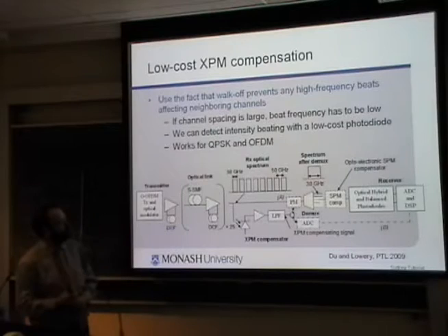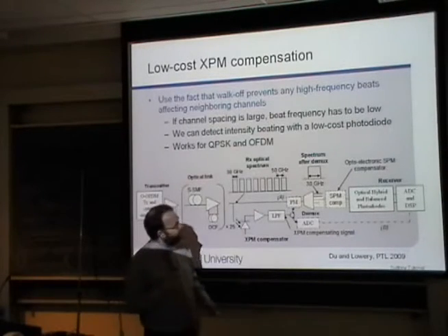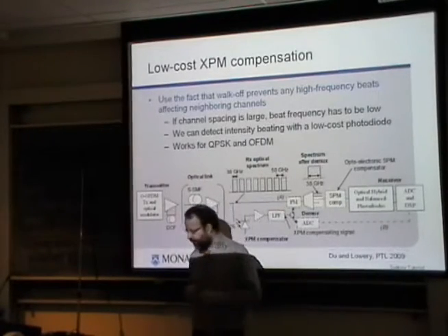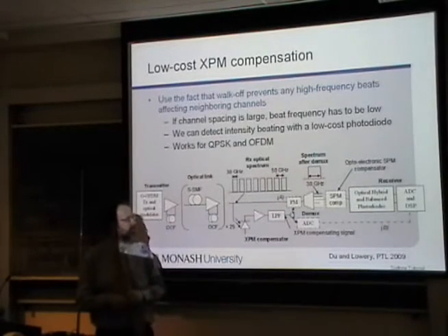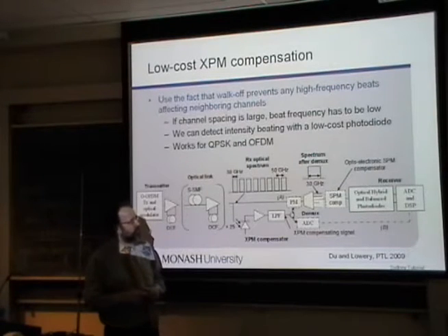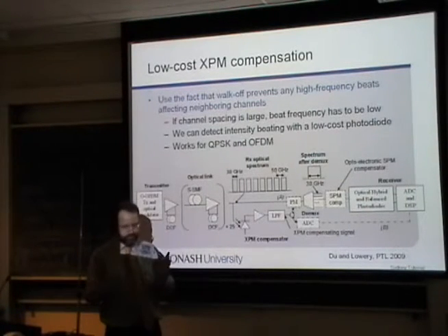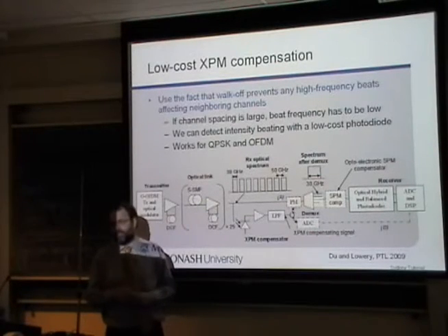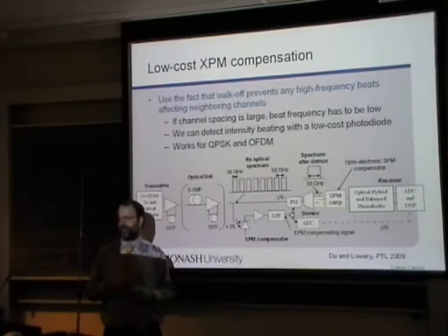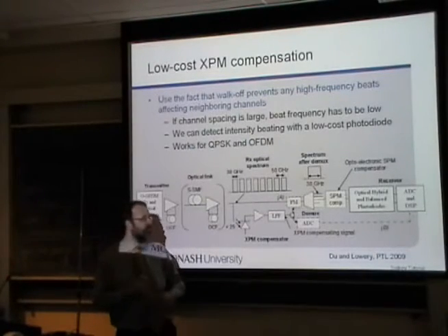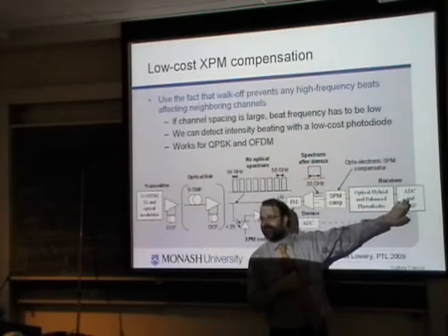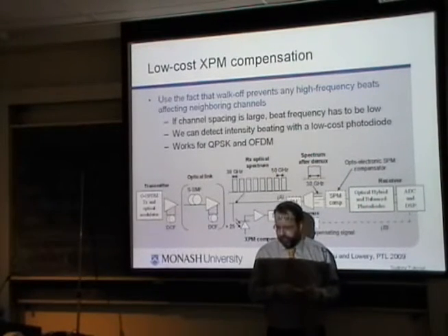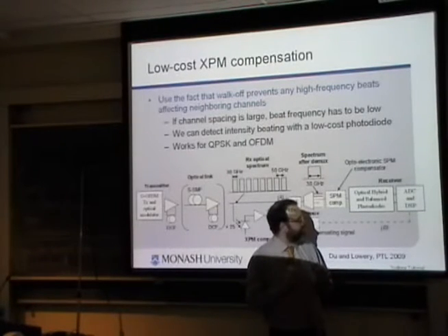So what's the problem with this? Well, the analog to digital converters. The current state of the art is 56 gigahertz samples a second, which, if you use IQ modulation, gives you an optical bandwidth that you can down convert of around 56 gigahertz. Their analog bandwidth is a bit less than that, but you can buy the front-end analog to digital converters to do 100 gigabits per second links.